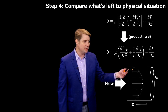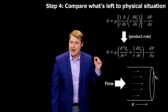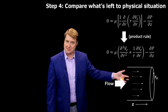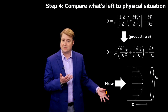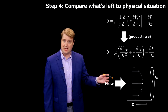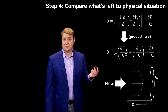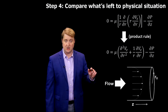We have to remember, if we look at the laminar flow regime, we're going to have this nice parabolic look to the way that the flow is going. It's going to be going faster in the middle of the pipe, and then it's going to be going slower toward the walls where there's a lot of shear stress, and we're going to have this curve in between. So yeah, indeed there is going to be a curve to that profile. So the second derivative of velocity in the z direction as a function of r is indeed going to be non-zero. We're going to have a curve there.